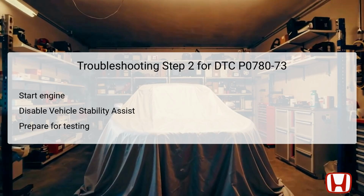Once the vehicle is secure, the next step involves starting the engine and disabling the Vehicle Stability Assist (VSA) system. Disabling the VSA is necessary because this feature could interfere with the testing procedure by potentially altering how the vehicle responds during acceleration. With the engine running, it allows for the simulation of real-world driving conditions, providing a clearer picture of the issues present within the transmission system.